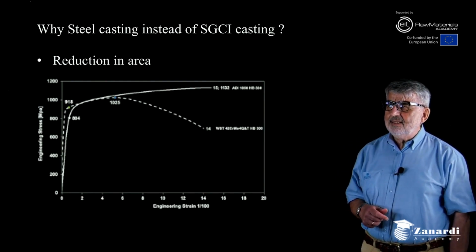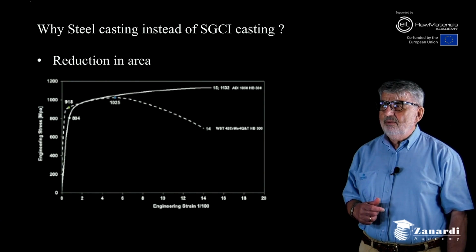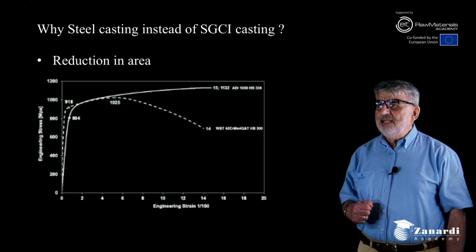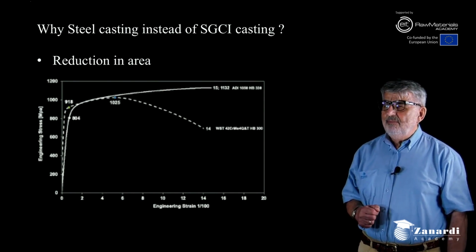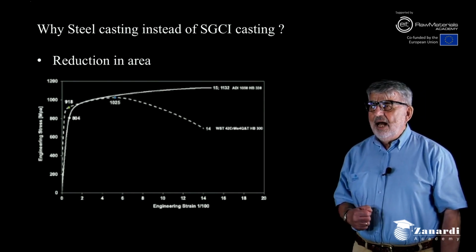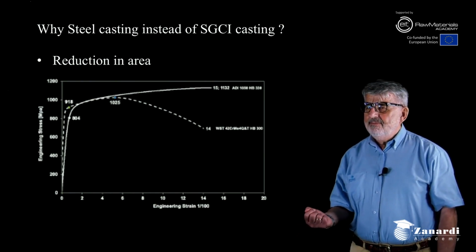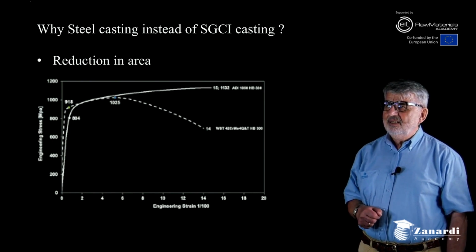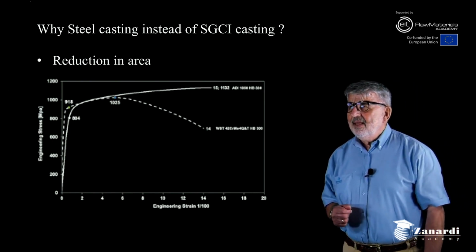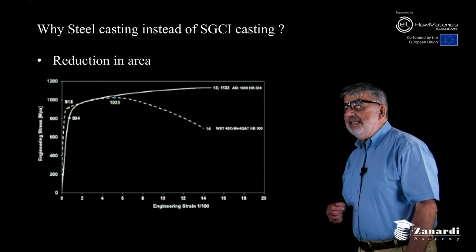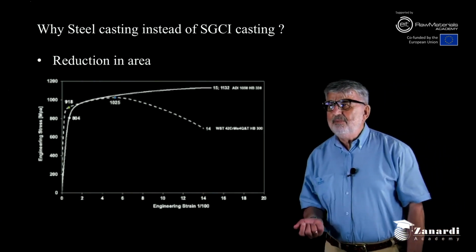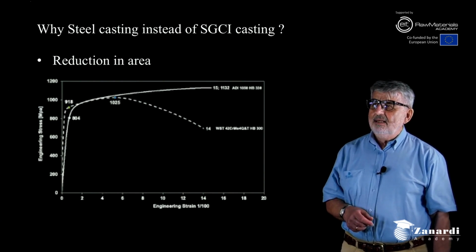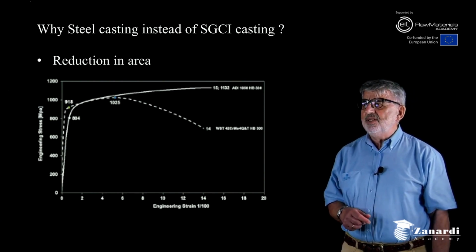A steel that is not breaking, but that will plastically deform, plastically go out of use, but without separating into two parts. And this depends on the necking behavior that is typical of ferritic steels and alloyed quenched and tempered steels.